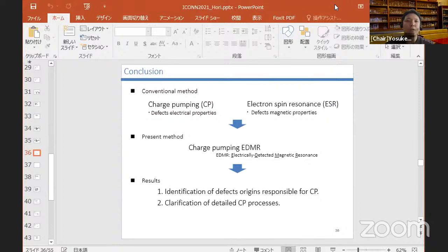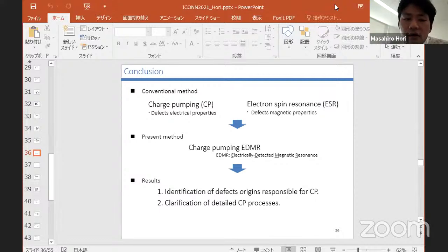Okay, so I have one question about the shallow state. In your study, your material has the shallow state in addition to the Pb0 state or any other states. So if there is no deep state level, is it possible to recombine the carrier to the valence band? It's a good question. The shallow state is not the recombination center.